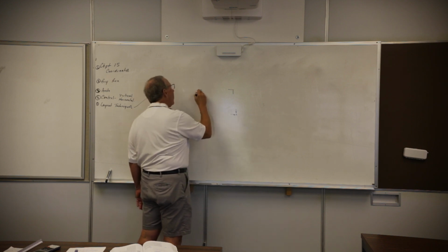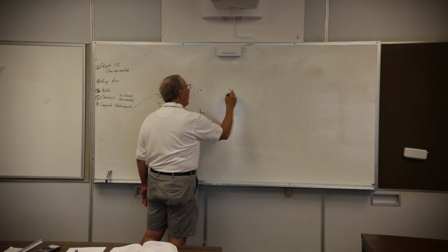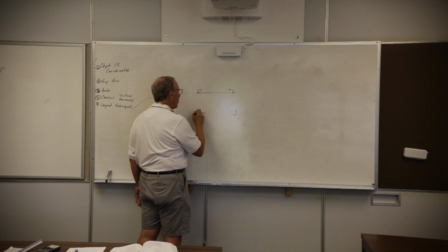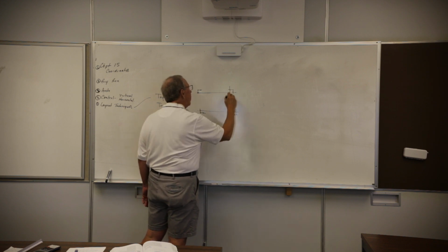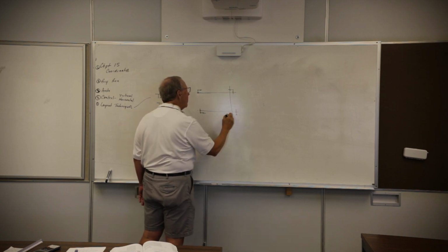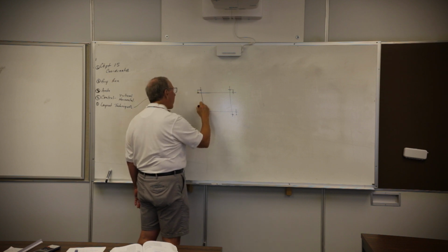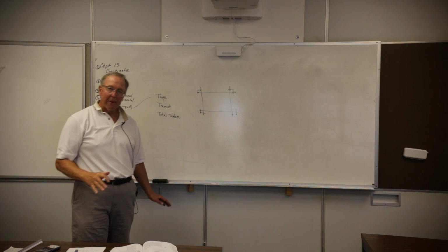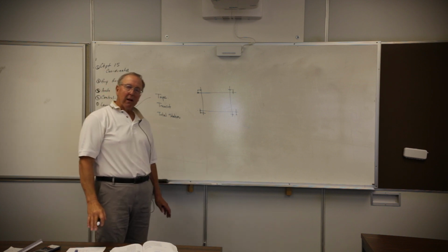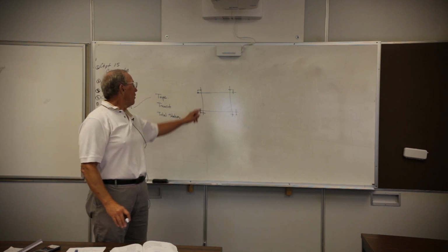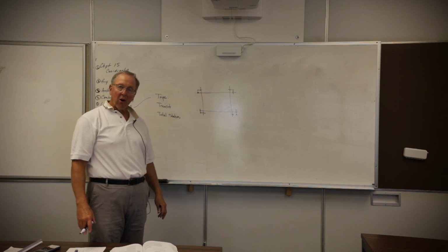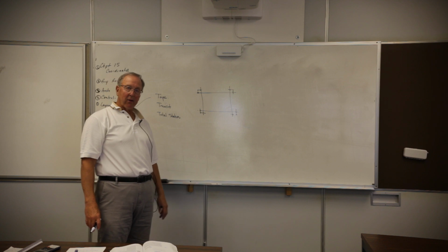That allows people in the field to take a string between the nails, and it ends up with a nice little rectangle. And that rectangle will circumscribe whatever you're laying out. And you can from there have right angles at these corners. You've got dimensions that are controlled by the drawing, and you can go ahead and lay it out.